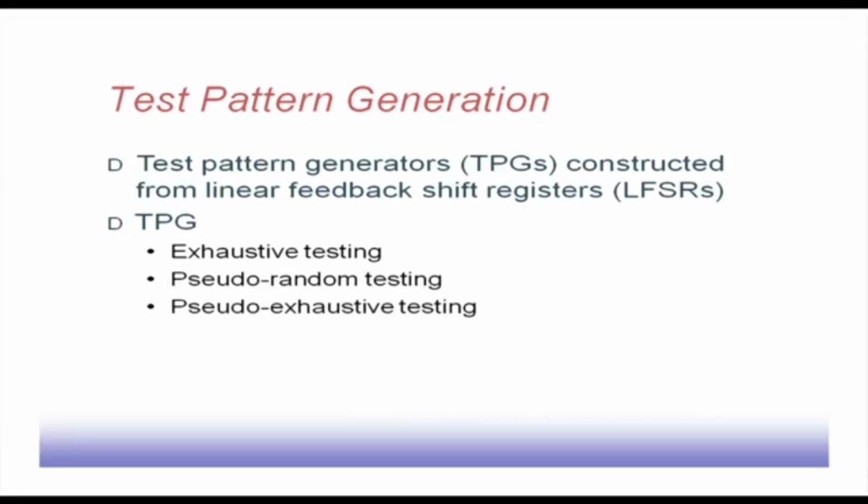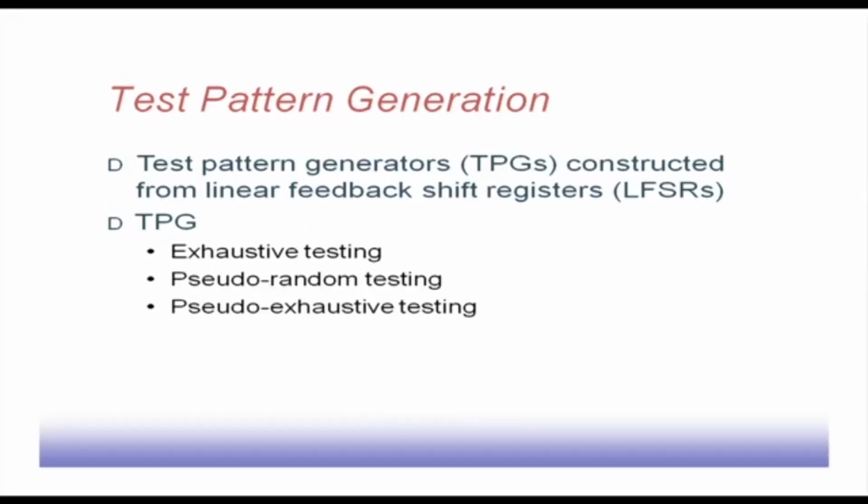Now, how can this test pattern be generated? Typically, a deterministic test pattern generator gives us a set of test patterns. As a test pattern generator, we can have a memory where all these test patterns are stored, and a counter that produces addresses for the memory, and at each count value it outputs one particular pattern that is applied to the circuit. That is the standard ATE type of operation, but when we are talking about BIST operation, we do not have such a sophisticated mechanism.